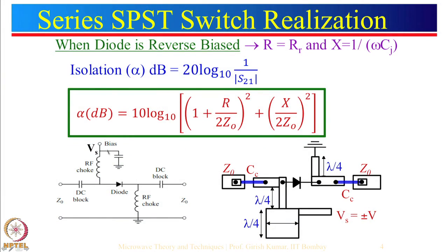Now over here there is still one small problem in this particular circuit. And what is that small problem? See, here we are not able to limit the value of the current. In fact, for practical circuits we should also put a series resistance over here which should control the current flowing through the diode.